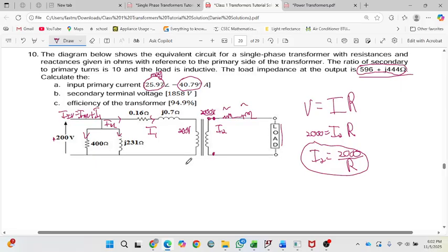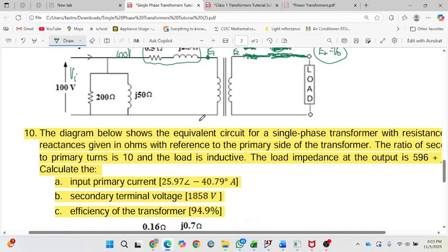So if I want the voltage here, you have the 2000, you have your REQ and your XEQ, normal circuit theory: 2000 minus the voltage drop across your REQ plus jXEQ, and that basically gives you a V out. Normal circuit theory, okay, you have 2000 here minus your losses, you get V out. That's all. Nothing to bust your brain.